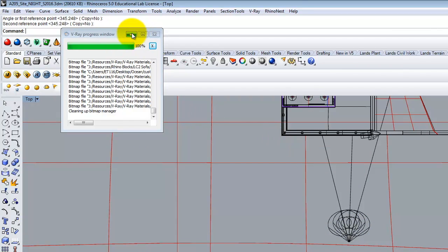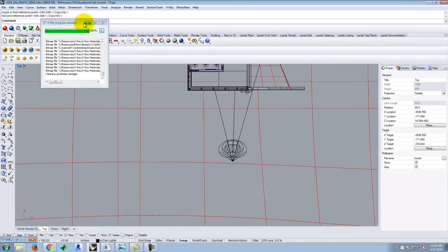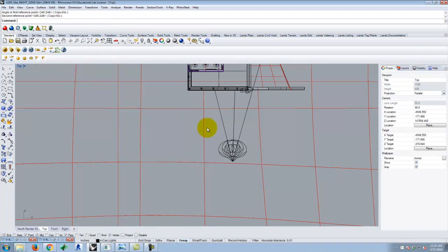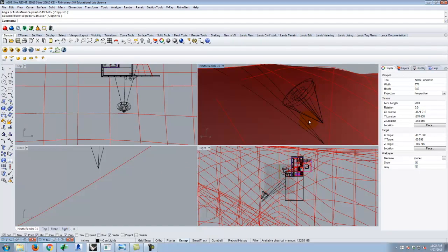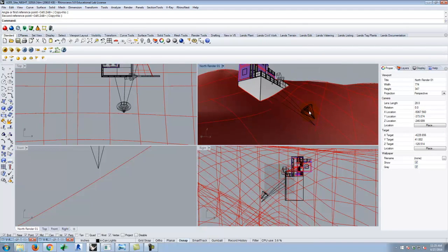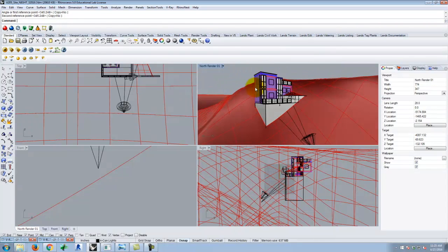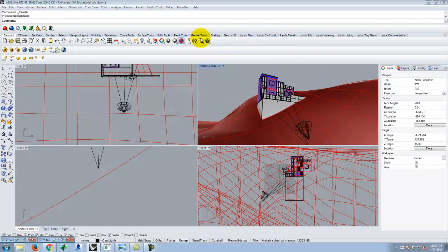Okay. The other thing that adds to the realism a little bit, and if it's a night scene, we don't have to concentrate too much on this, but where I choose to place a little bit of grass can make a big difference. So if I were to place, for example, a little bit of that bunch grass right down here in front of the lights, that would cast some shadows on the building and make it a little bit more realistic. So beyond just doing this view and confirming that my render works and I'm getting good lighting on that side of the building, I may drop in a little bit of grass in front of these lights just to add a little bit of shadow as that casts against the overall building.